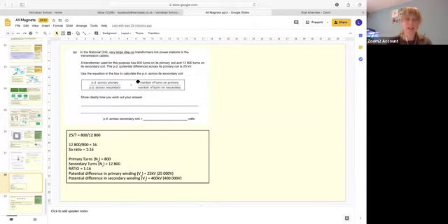So using the same understanding of what I've done before, where am I putting my numbers with respect to these here? I want to put a value next to each descriptor and see which one is missing. I start off with the first thing that's given to me: a transformer used for this purpose has 800 turns on its primary coil. So at this point I'm going to write 800, which is what I've done here. And it has 12,800 on its secondary coil, which is here. So this divided by this is the same as this divided by this.